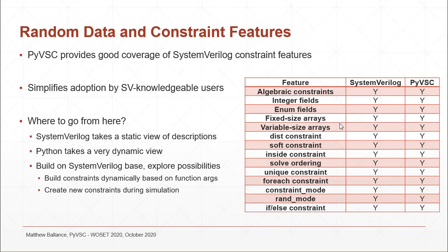Now, PyVSC actually has very good coverage for the SystemVerilog constraint features and the SystemVerilog-style data types. Here's sort of a summary of the feature support. This makes it very easy for a user that's knowledgeable in SystemVerilog to pick up the feature set and make use of it in much the same way that they're used to using SystemVerilog.